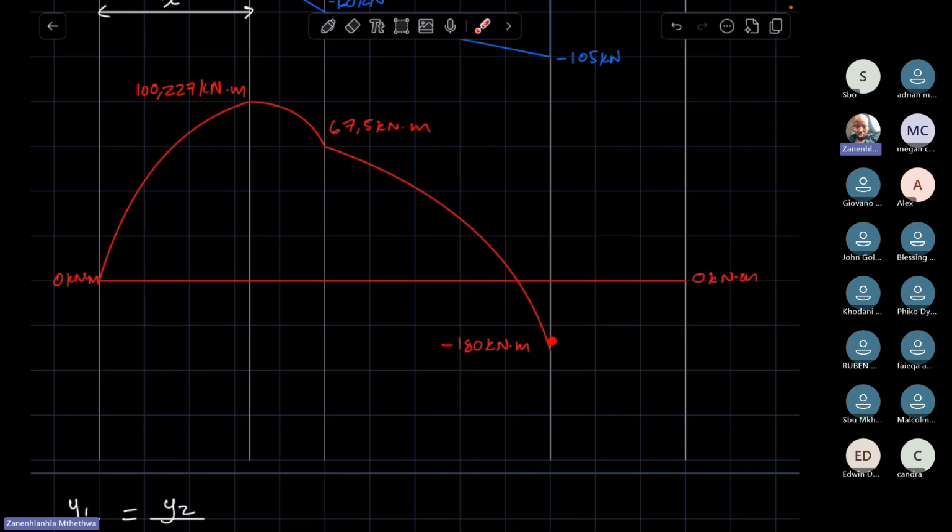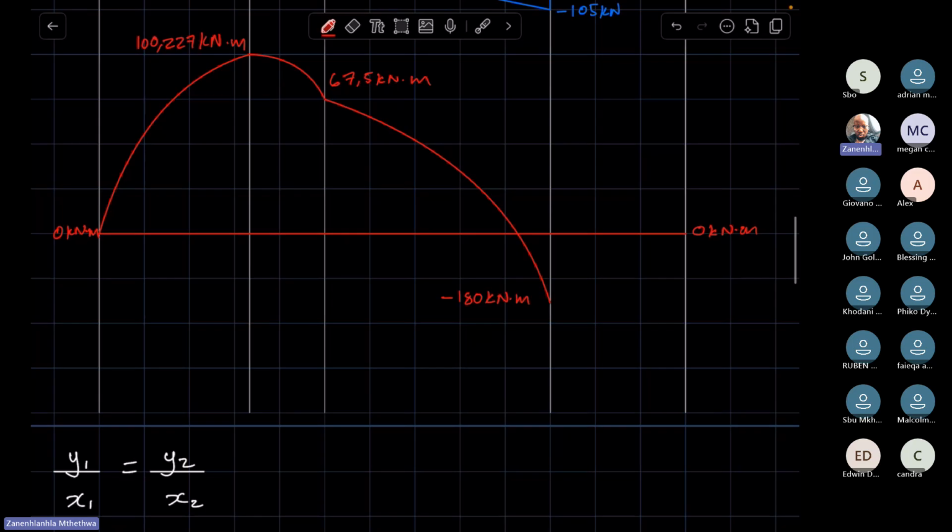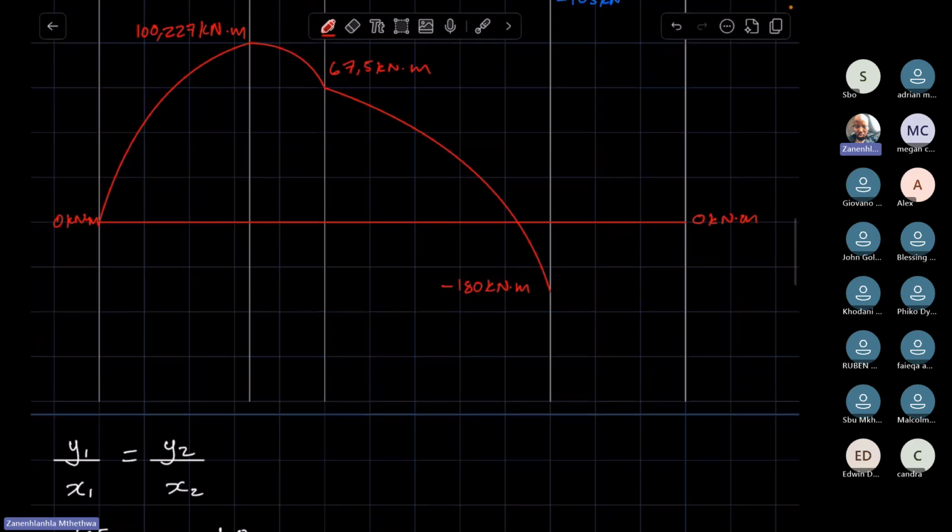this point, we draw from here to there, you don't necessarily have to show that. In fact, if you think about it, say our bending moment from here to some point here was negative, you're going to draw a line going like that.